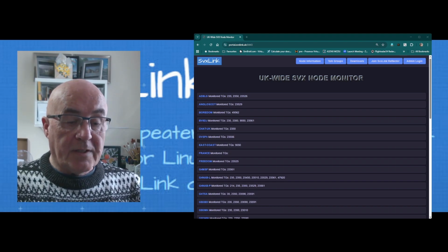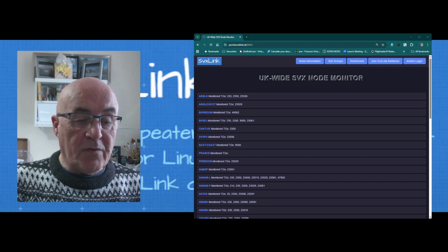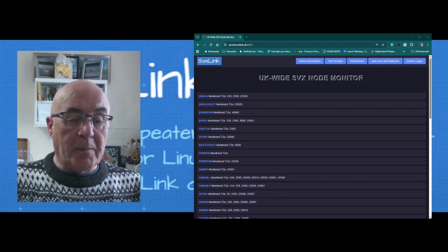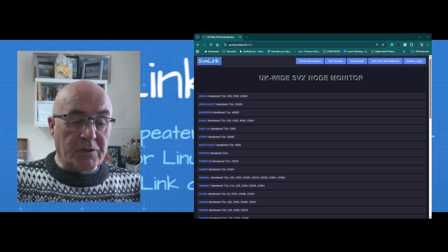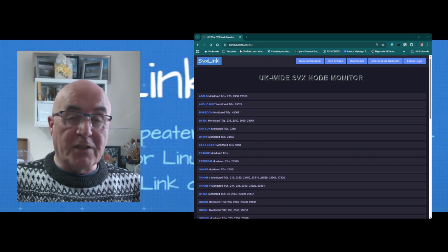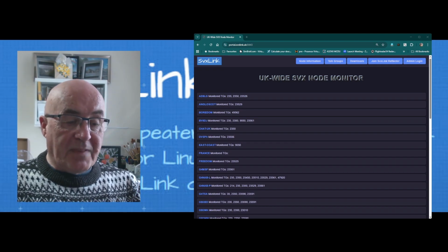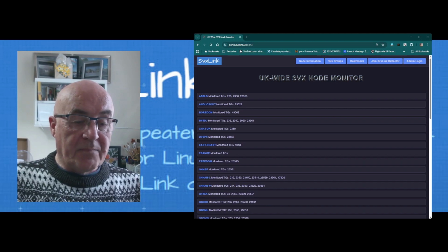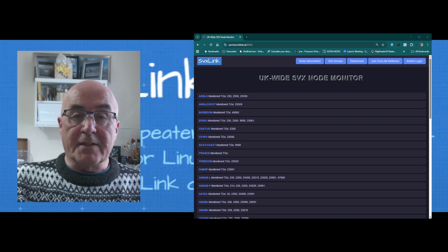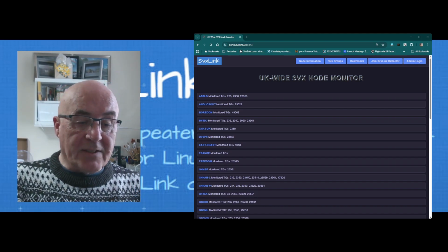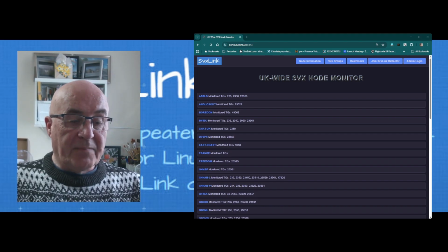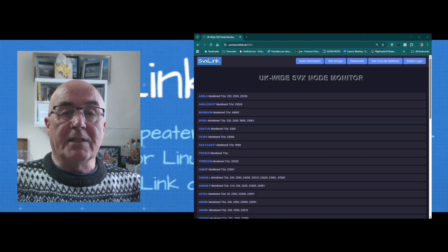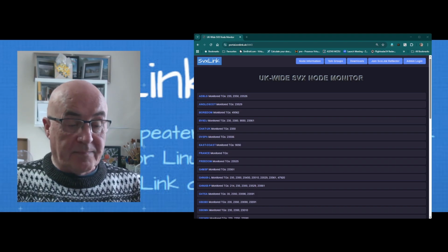So in order to provide additional links to the networked reflectors, Lee and I have made instances of only reflector logic coupled with USRP logic and linked them to AllStarLink or DVSwitch nodes as fixed talk groups. That is to say that they are always live, and to enable them on a local repeater, the sysop simply adds the talk group to the monitoring list, and whenever the AllStarLink node is active, it wakes the repeater or repeaters.